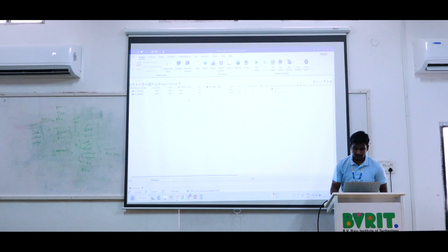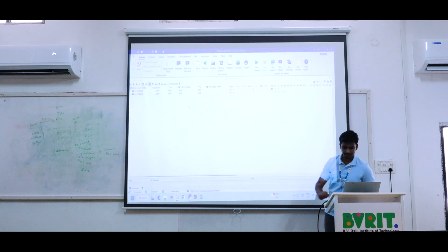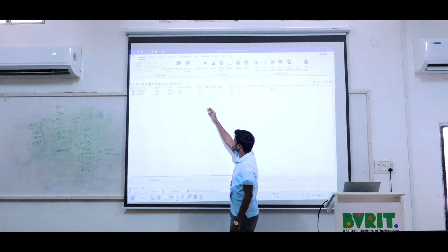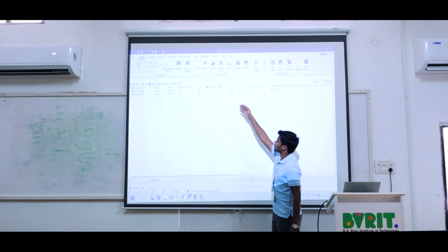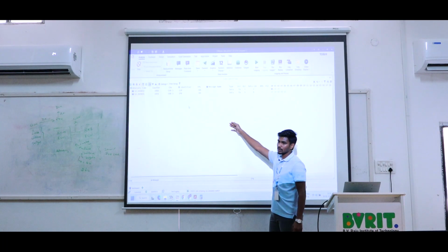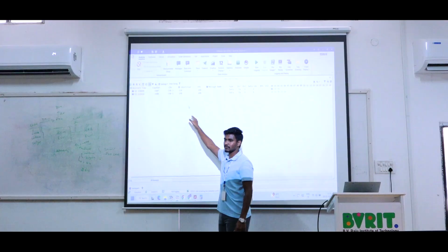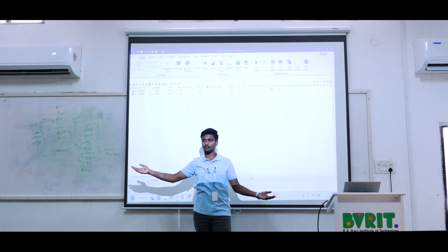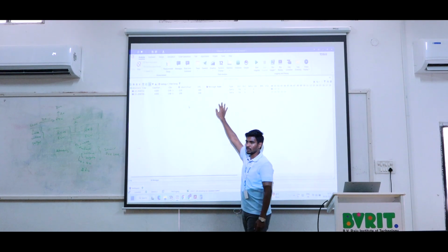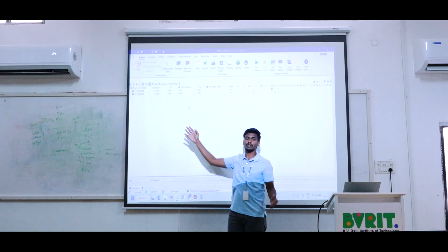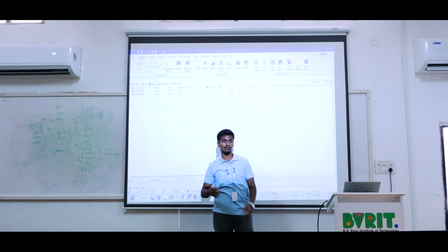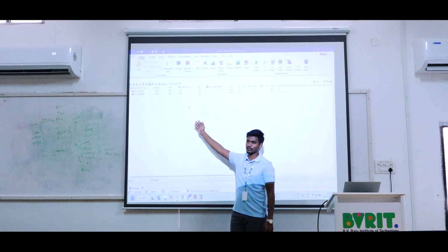Here you can see it's just showing ID number 120, it is showing the FPS we have set here, but it is not showing any message name. So we are not able to identify which message is transmitted where. Where is the fault detection? Now it is showing an error, which means a fault was detected, a fault or error message like that. But we don't know where the fault is detected, or which message detected the fault.